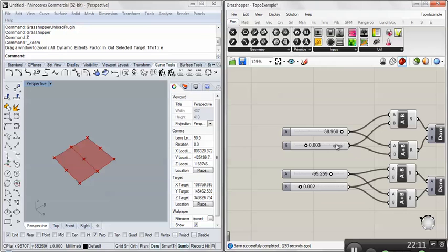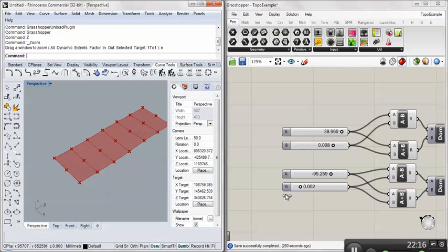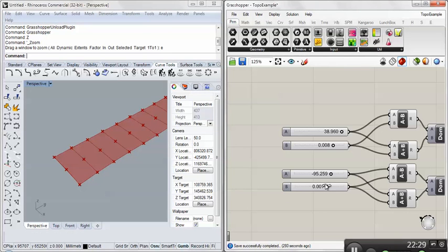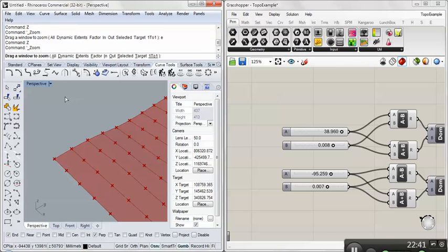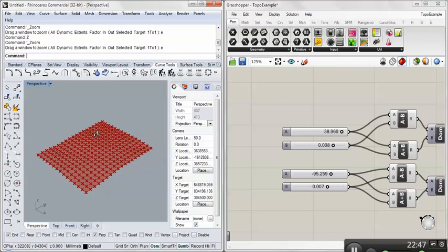I'm going to go ahead and increase this resolution a little bit. Is there any reason why it would show up in the top view and not perspective view? Zoom extents. If you click on the perspective view and do zoom extents, you should get it centered there. I have set some extents. I type Z and then E. And there you go.